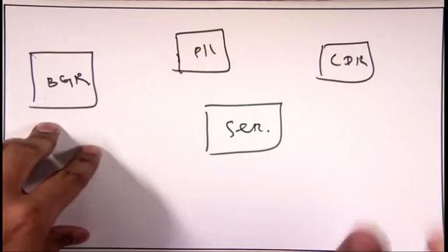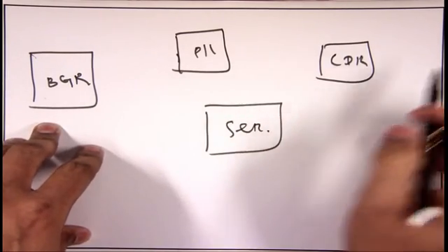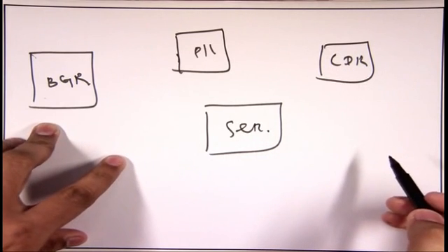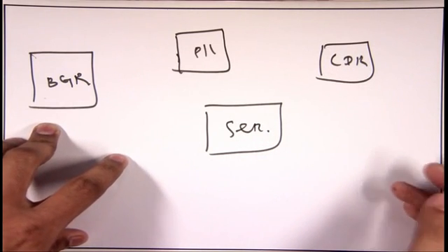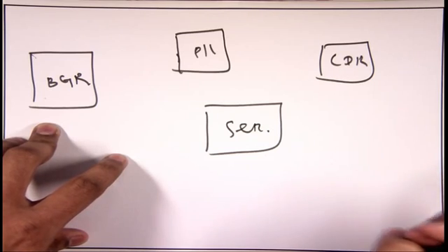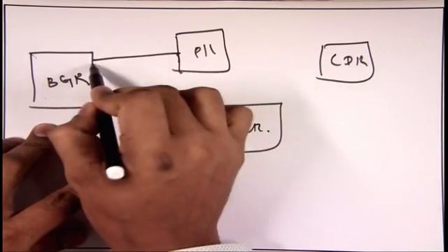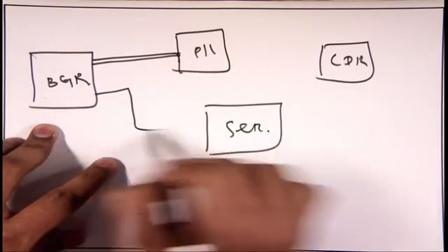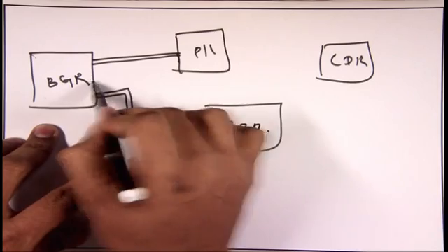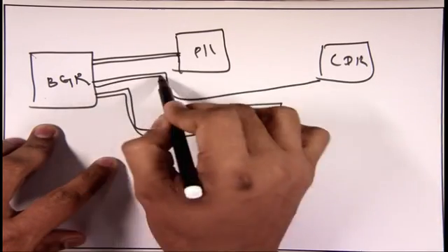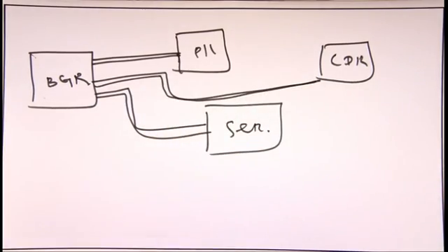So PLL is the phase lock loop and there is a clock data recovery circuit. The mixed signal floor plan. So how will the band gap reference be routed? Explain. For the PLL, one line will go, for the BGR one line will go for power, and again for the CDR one line will go. So it may cover a lot of distance.